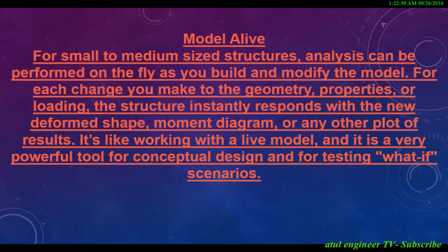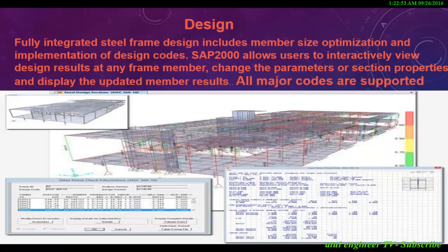Model alive. For small to medium-sized structures, analysis can be performed on the fly as you build and modify the model. For each change you make to the geometry, properties, or loading, the structure instantly responds with a new deformed shape, moment diagram, or any other plot of results. It's like working with a live model, and it is a very powerful tool for conceptual design and for testing what-if scenarios.